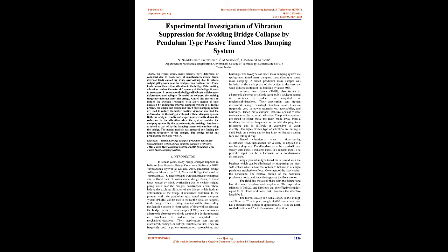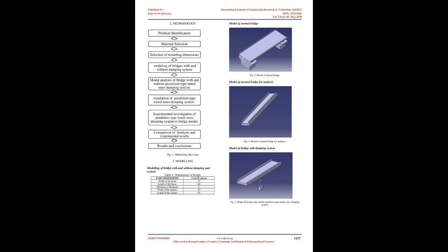These bridges were deformed or collapsed due to flood, lack of maintenance, design flaws, external loads caused by wind, overloading due to vehicle weight, piling work near the bridges, construction error. These induce exciting vibration of the bridge, which leads to deformation of the bridge at resonance condition. In the present work, the pendulum type tuned mass damping system, PTMD, will be used to reduce the vibration that happens in the bridges. This exciting vibration will be absorbed by the damping system in a short period of time without damaging